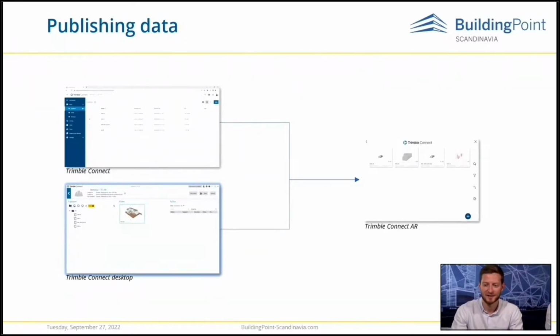We need to know that Trimble Connect AR, unlike the XR10, our HoloLens helmet, displays one model at a time. So if we would like to see objects from different IFCs, like ventilation, structure, and architecture, we need to combine them. Luckily, there is an easy way to do that using the TrimBIM format. TrimBIM is a file format invented and implemented in Trimble for efficiently storing geometry and attributes. It speeds up the BIM process and can combine many IFCs, which is important at that point.